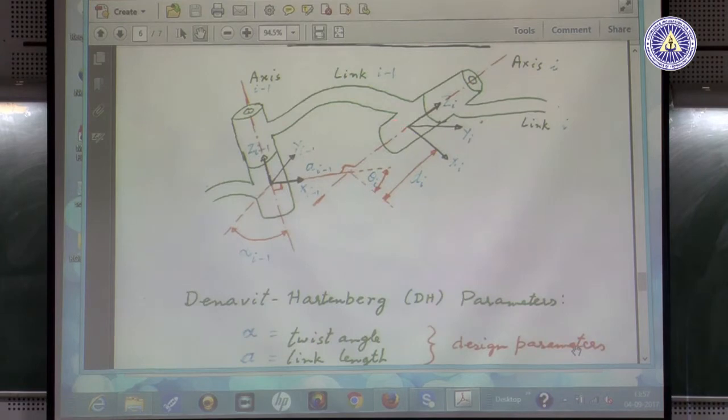That will be the fourth column of the transformation matrix, in the description of the pose, or position and orientation, in the homogeneous transformation. And then you have to say what is the description of the x axis of this frame, that is, this unit vector, in this x y z. So, some 0.75 in this direction, 0.32 in this direction, and something 0.23 in this direction, whatever it is. Whatever this is, whatever this is, whatever this is, they will form the 3 columns of the rotation matrix in the transformation matrix.